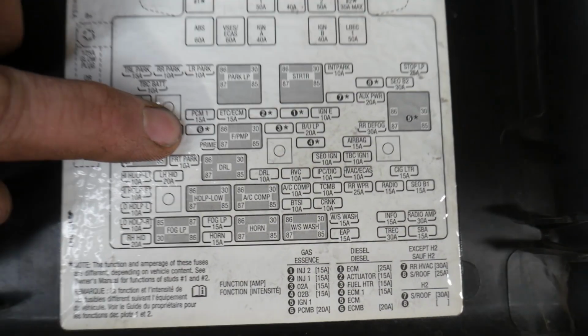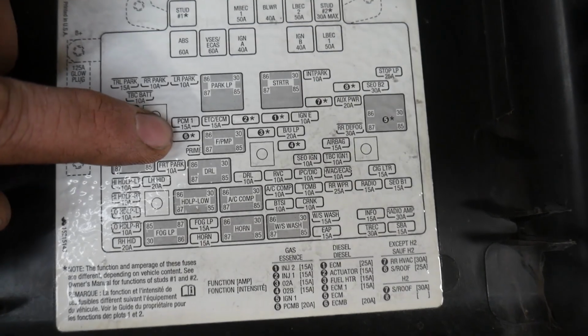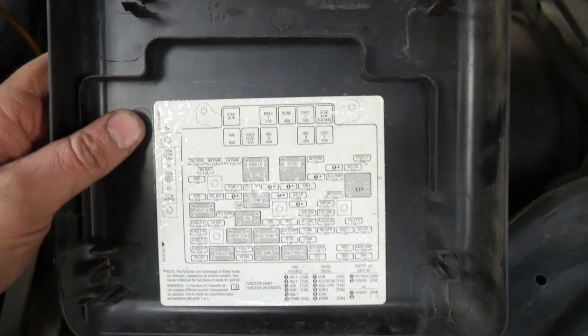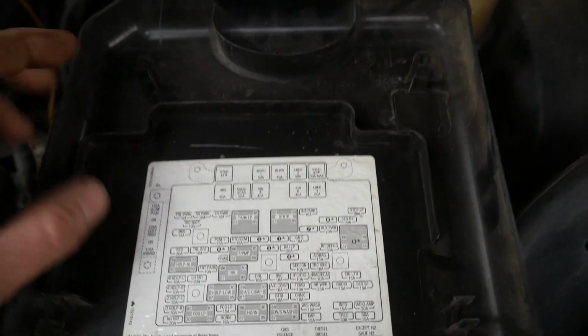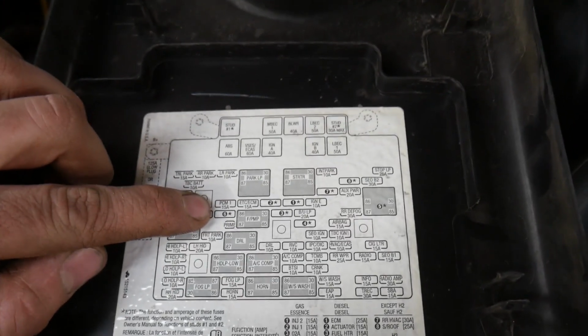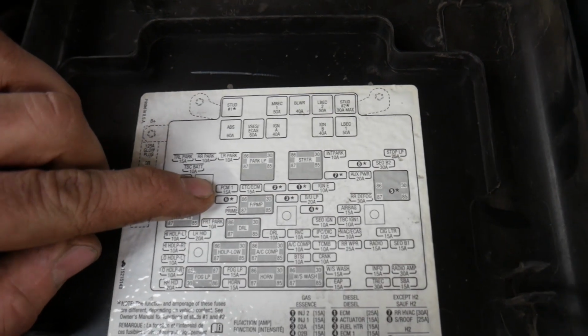So I looked at the schematic. That one is PCM1, what's labeled on here. And it says 15 amp, but in the diagram it showed a 10 amp. So this lid may not be the right lid. I pulled the fuse diagram for this vehicle, and it shows ECM1 fuse in that location, and it's supposed to